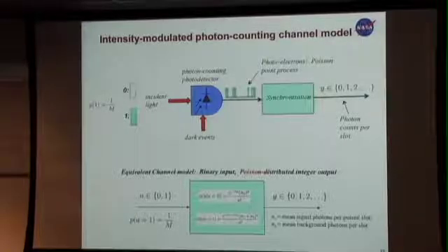You transmit it, and all sorts of funny things happen to it along the way. And finally, you detect it with a photon counting detector, which could introduce noise; there could be some noise coming in from the channel. There are dark noise events introduced at the detector. Synchronize it properly, and you count some photons. The channel model for this is a Poisson channel model. What you get out of here is dependent on how much power you put into it, and that's the mean of a Poisson process that tells you the probability.